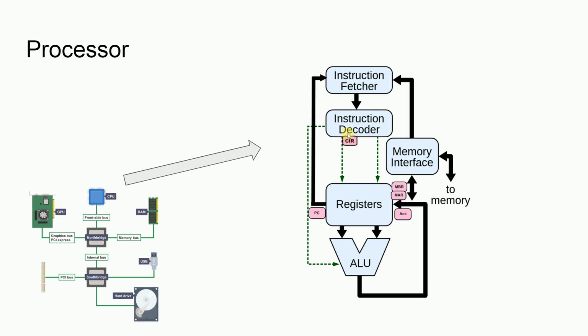And the instruction decoder then works out what needs to be done by holding that instruction in a register. So we've got the current instruction register, so that different circuits can be connected. It also may request that there's further information received into the memory as well. And when we come in here, we might need to actually access memory at its address, using the memory address register. So if I want to go to a certain location, I use the memory address register, and that connects up that particular piece of memory.